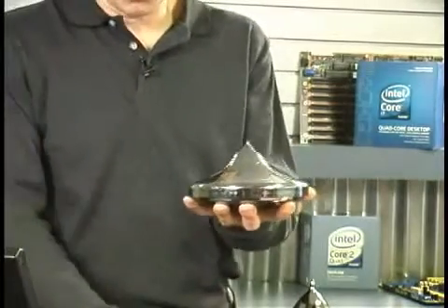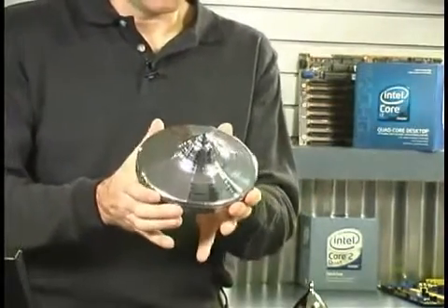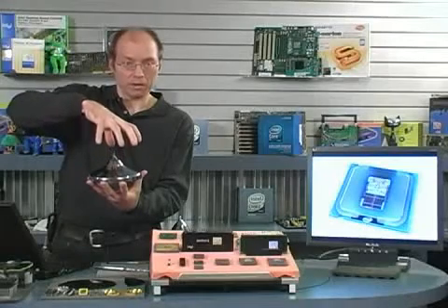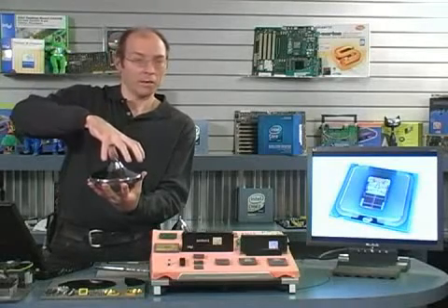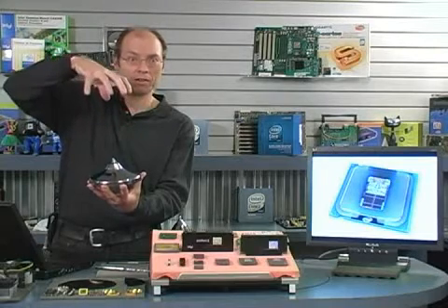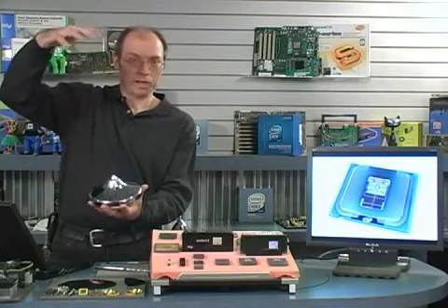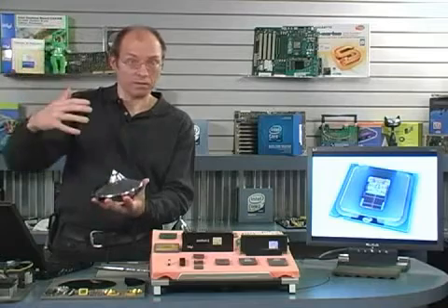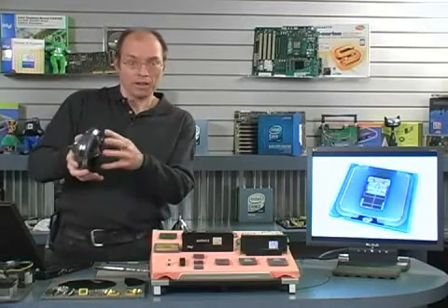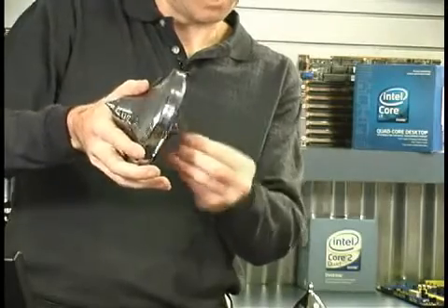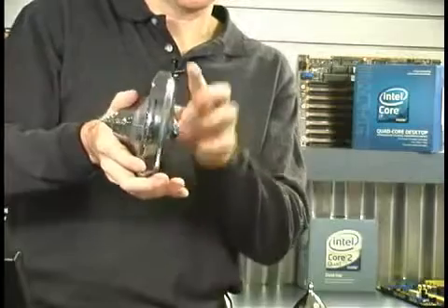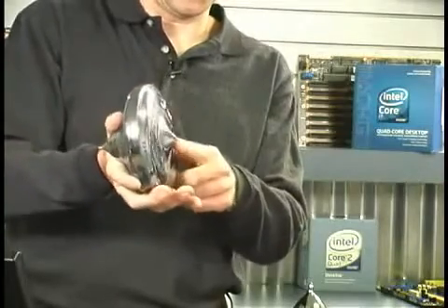Now, once the crystal reaches the diameter that it is intended to be, then the process speeds up a little bit. It's pulled out a little bit more quickly until basically what we have is a cylinder. Imagine a cylinder of this crystal material being pulled out of this vat. Once the cylinder has reached its final length, which is usually a couple of feet long, then the pulling process goes more quickly and we end up with a tail. They want a gradual pull-out of the material from the vat to prevent any kind of thermal shock. Now, the tail on this crystal is very short. It's very short here, as you can see.